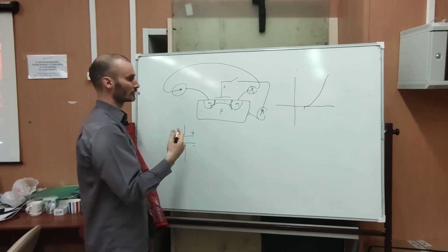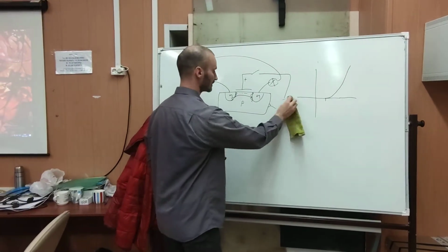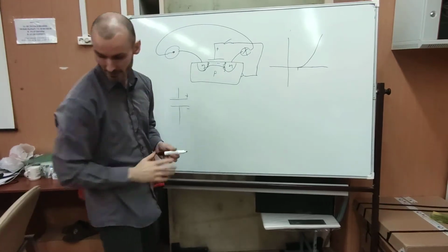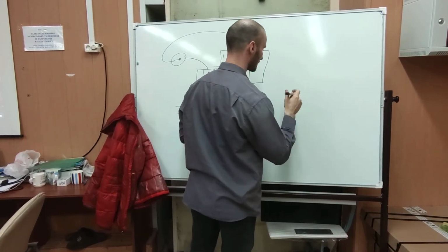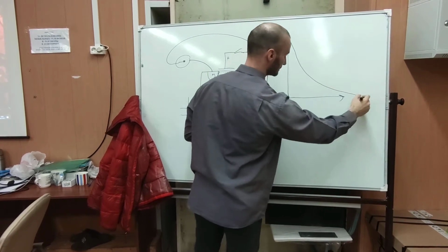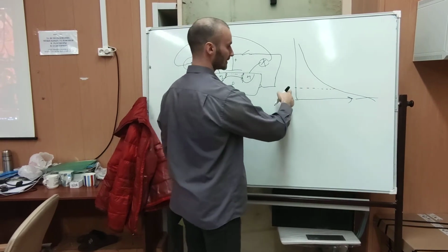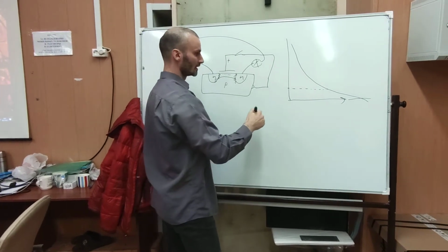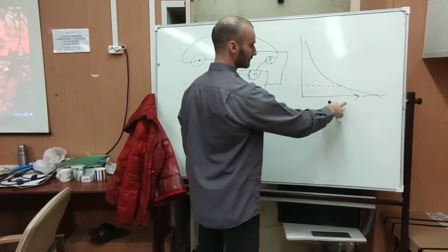Okay, so one way to discharge the capacitor is to link the substrate to the gate. So we can simply link them together. What will happen in that case? The discharge graph will look like this. That will be time, and that will be charge. And charge will drop like this, so not to zero. From this voltage, which is the voltage at which you stop having the channel, it will stop conducting and it will switch off. But that wouldn't happen fast enough.